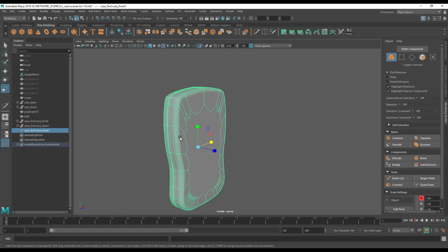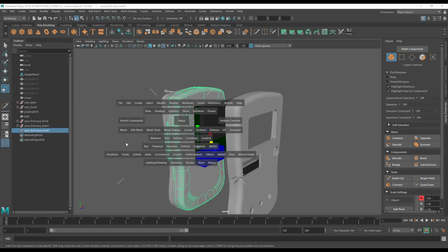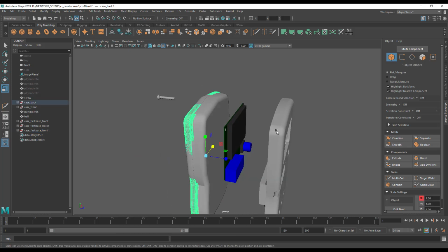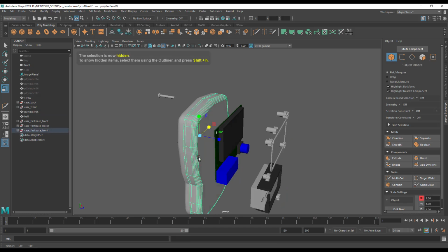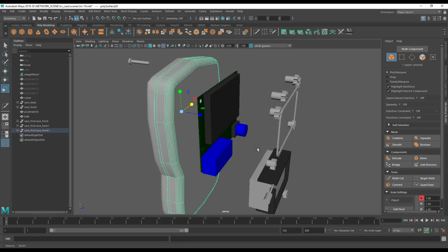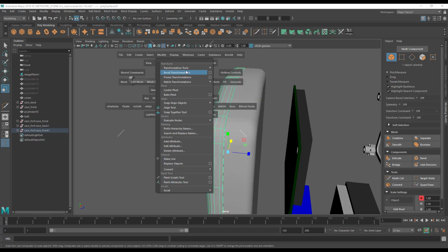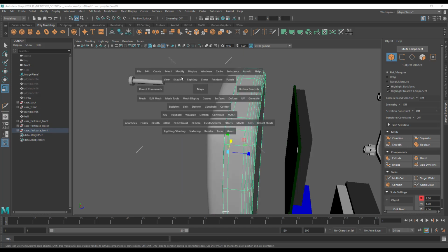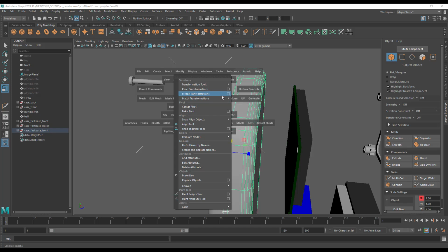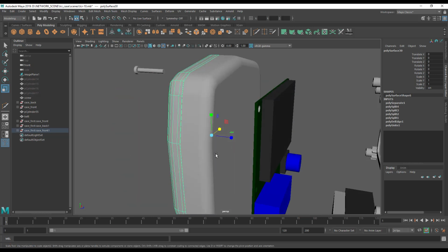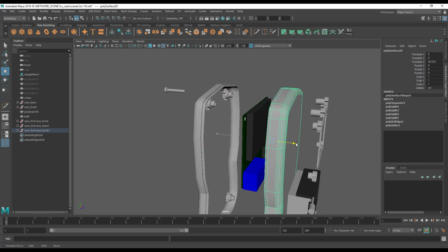Now your problem here is going to be, let's go to Control 1, mesh separate. There we go. I'm going to hide this part and hide this part. Now your problem is, of course, and these should be separated again, while we've got them in the location that we need them in, let's do a modify freeze transformations. Done. And same again, modify freeze transformations. Done. So just to reiterate the point again, if I move this around, I can easily move it back.